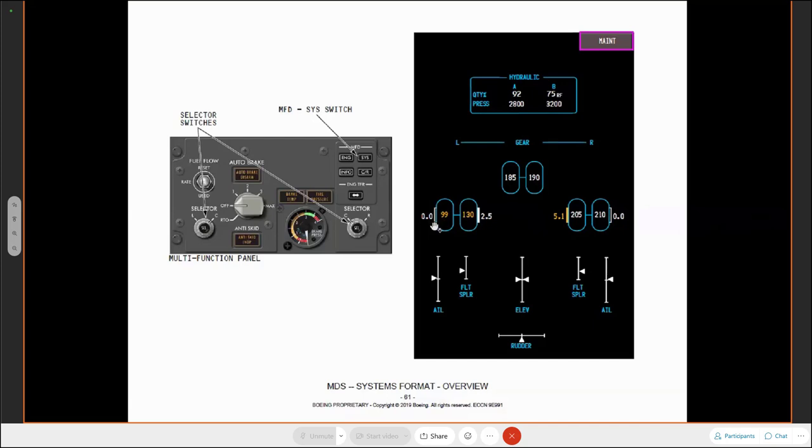As I apply the brakes and use the brakes, they're going to become hotter. This digital readout is going to start to increase, in what we call scalar units. They go from 0.0 to 9.9. Brian will probably correct me, and I shouldn't say these things because it's not really my area, but I think 9.9 is about 750 degrees C. So quite a hot brake if it gets to 9.9.